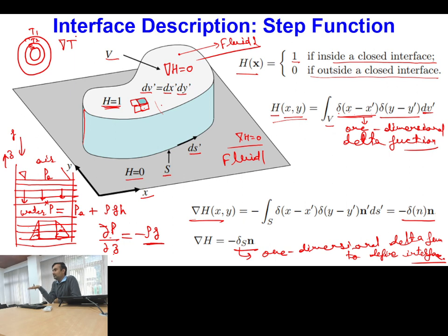Minus K into the gradient of temperature. Okay. We always say that isothermal lines and heat transfer lines are normal to each other. So it means the gradient of temperature will point in a direction which is normal everywhere, always normal to the uniform value of the temperature. Is this point clear?